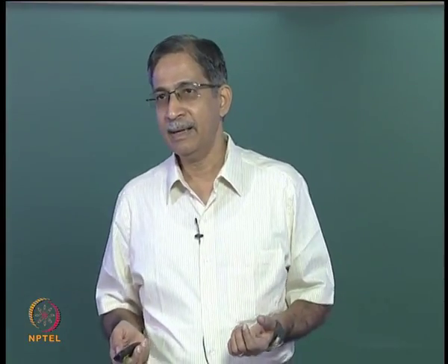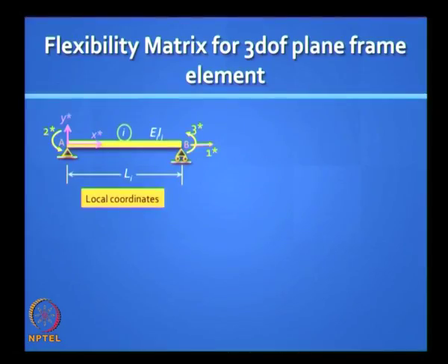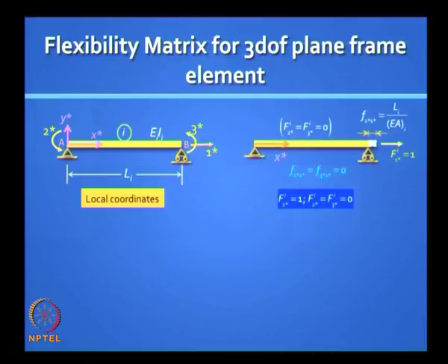Okay. First you need to identify the degrees of freedom. You know that it's the same as you use for the reduced stiffness method, 3 degree of freedom system. You can generate the flexibility matrix from first principles. You apply 1 unit load at a time. Here you apply loads. You can do one thing, you can take your stiffness matrix and invert it, you will get the flexibility matrix, but that's no fun. Flexibility is for people who want fun, because you want to understand exactly what's happening.